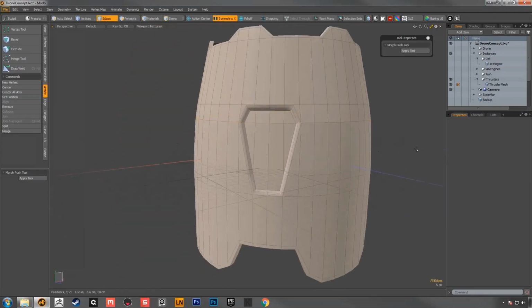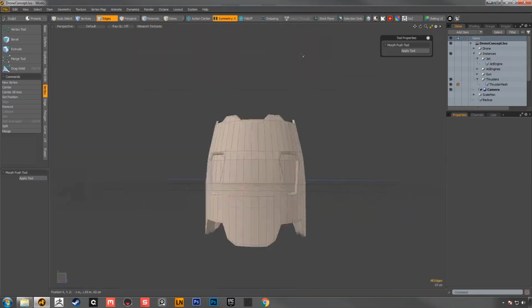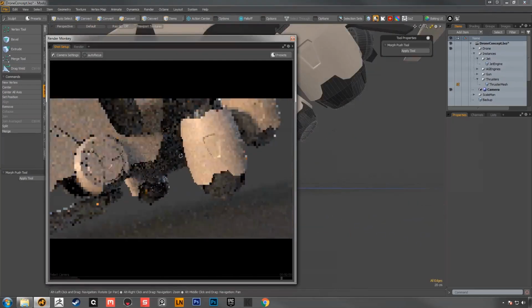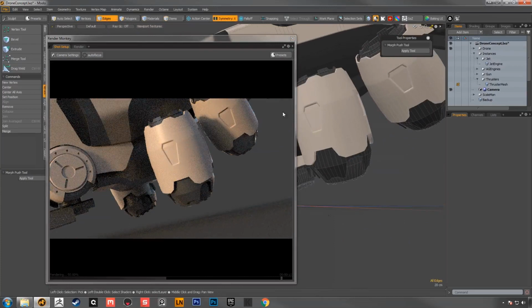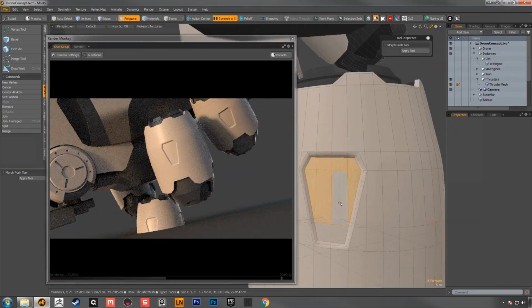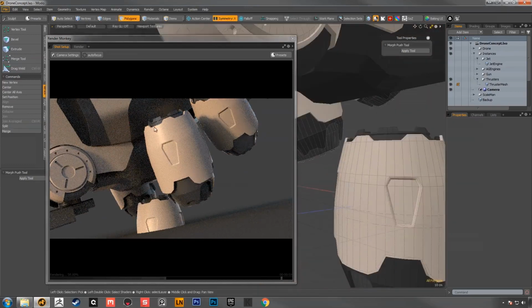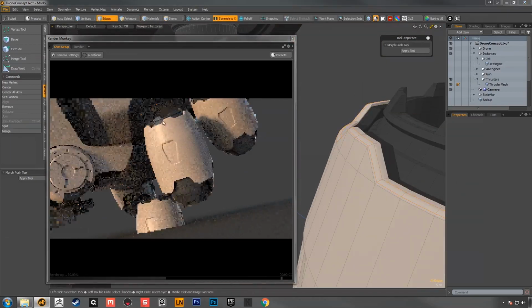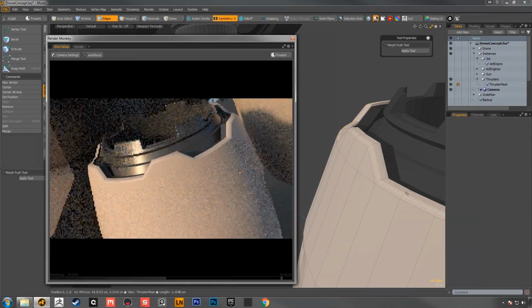But the problem with this kind of shape is when you're modeling it into the face of a curved asset, it's very easy to get normal errors. So that's why I'm spending more time here trying to see how much extra information I need in the modeling, and also keep adjusting the actual normals until it looks correct, because I don't want shading errors.